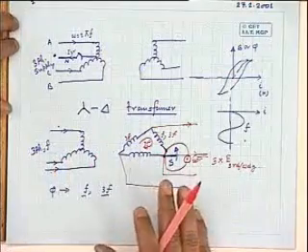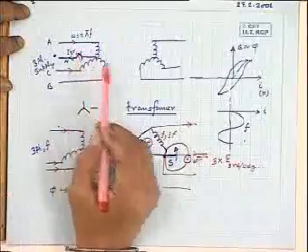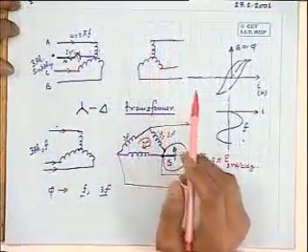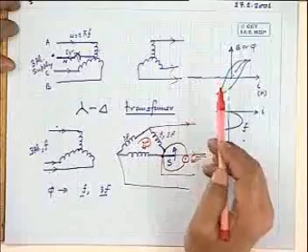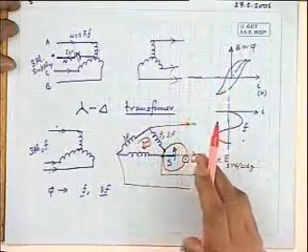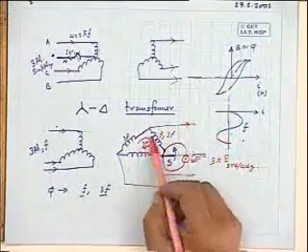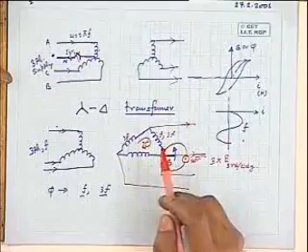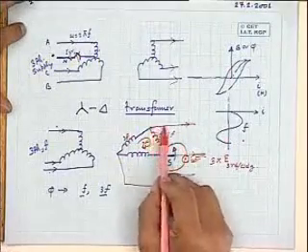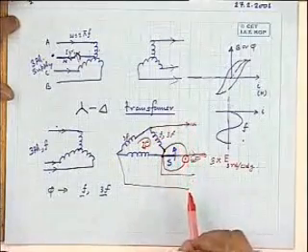Therefore, delta winding transformer, whether this neutral is connected or not, it tries to make the flux sinusoidal on its own. You need not worry about it. Unlike in a star-star transformer with neutral not connected, here no third harmonic magnetizing current can flow. It cannot exist in the lines. It is as simple as that. However, in a connection where delta circuit will be there, the transformer by a self mechanism will try to circulate a third harmonic current and therefore try to make the flux sinusoidal in the core of the transformer, thereby solving somewhat the problem of non-sinusoidal voltage between the lines.